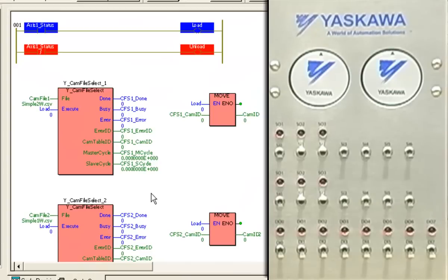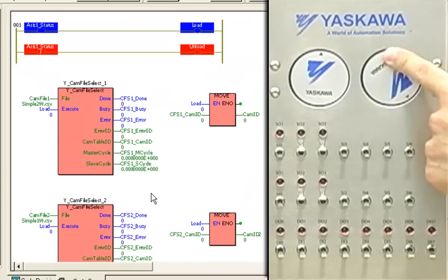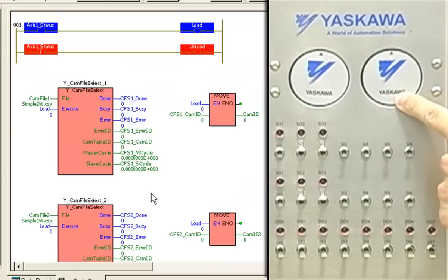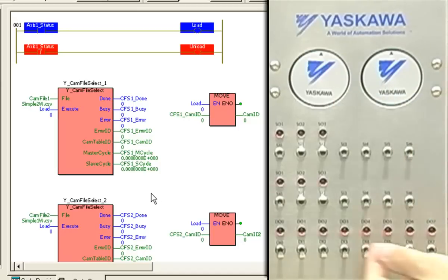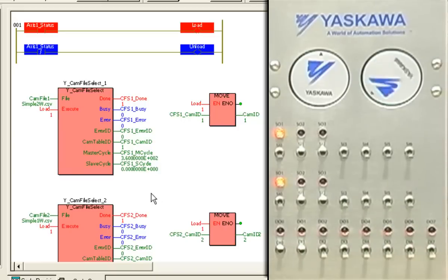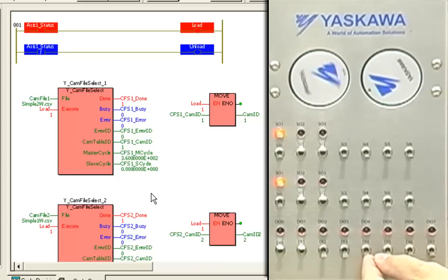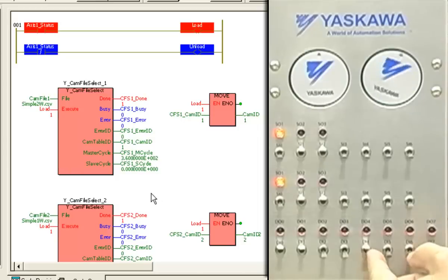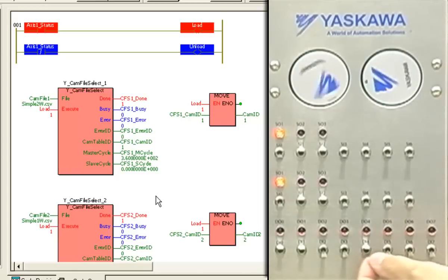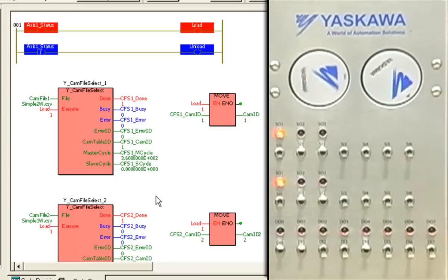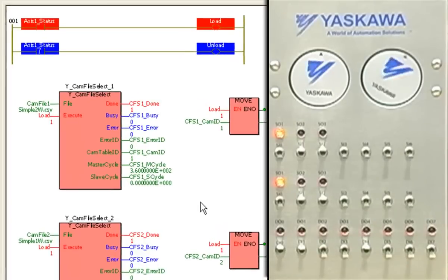Okay, over here on the demo kit now, it's ready to go. And by the way, I like to start these out up at 0 position. So now you can enable the axes. We can start our master moving again. Engage our cam with input 2. Now input 4 is our selector. So right now it's running the 2-way cam. If I flip this up and retoggle my cam in block, it now runs the 1-way cam on the fly.